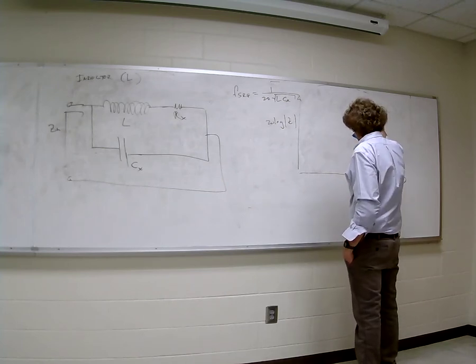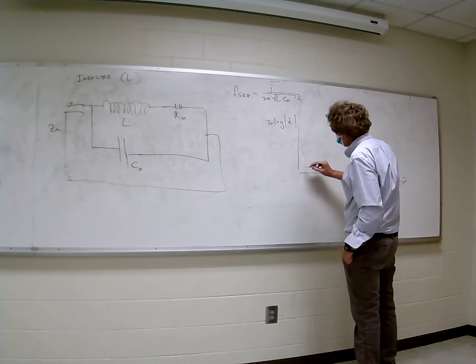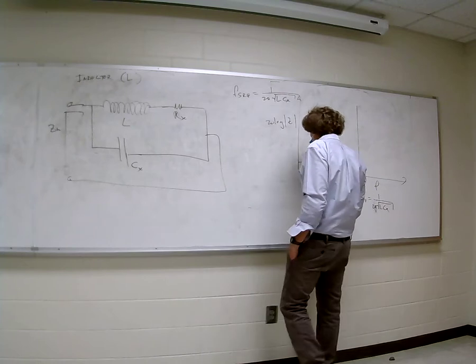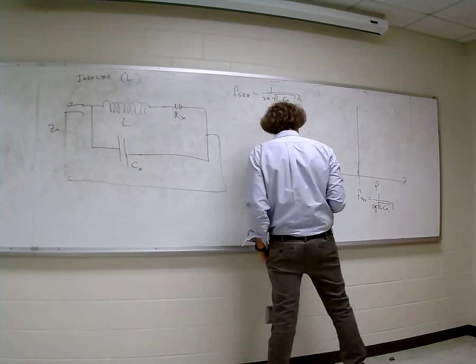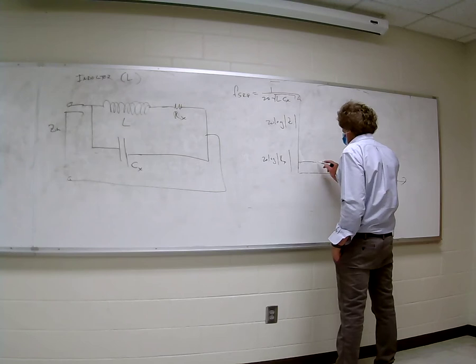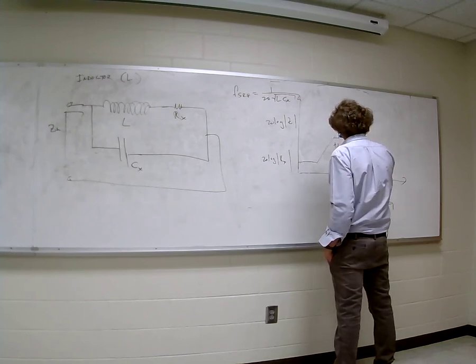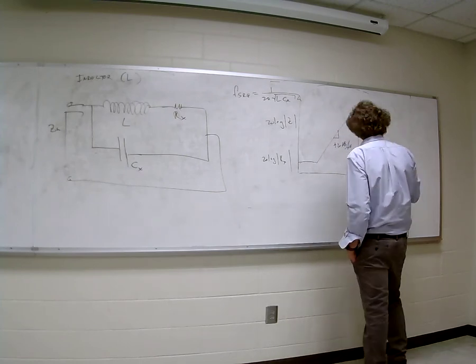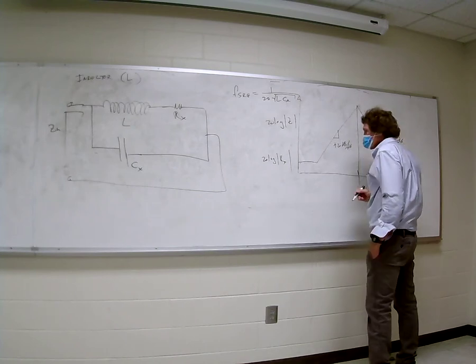Right here. And here's what happens with an inductor. No matter where you start an inductor, if you start at absolute 0, it'll come in at 20 times the log of the magnitude of Rx, the parasitic resistance. It's very low. And then it's going to start going up at a rate of plus 20 dB per decade until it hits self-resonance, then it falls down. It keeps going down at a rate of minus 20 dB per decade in this direction.